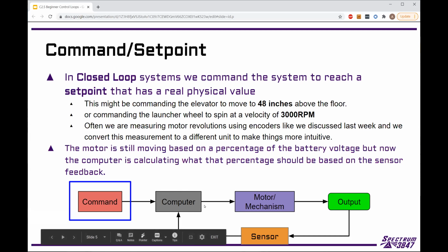We had a question of when would control loops not work. So the control loop may not work if somehow a sensor failed. Maybe the sensor isn't reporting back information anymore, a wire came undone, something like that. There could have been a software problem. Maybe somebody updated the software incorrectly and we got a bad value somewhere, and now it's trying to do something, but it's not actually tuned in properly.